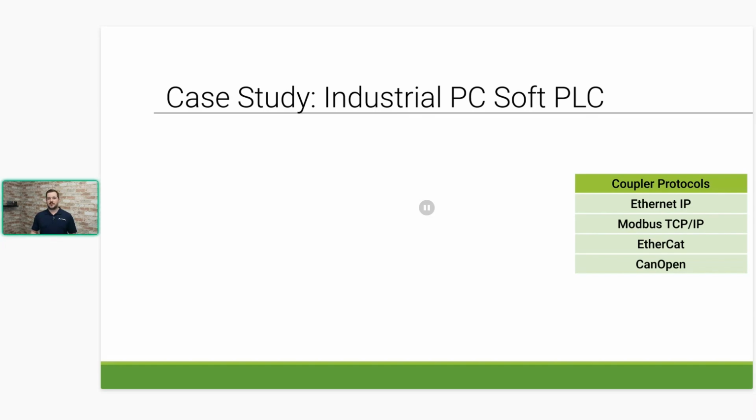If that does happen, you can connect that to the Easy Remote configuration software, which we will showcase here in a little bit as well when we do the demo. And that will tell you what error code you're getting, and then you can look up that error code in the IR module manual. That will tell you what's happening there.